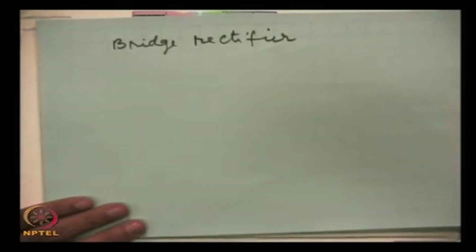The bridge rectifier is also a full wave rectifier, but as you will see, I draw the circuit, it makes use of 4 diodes and a transformer without center tapping. This is the circuit.